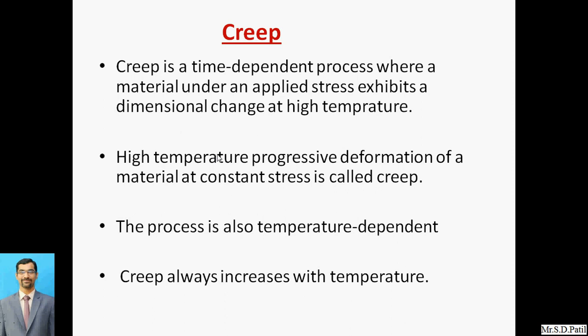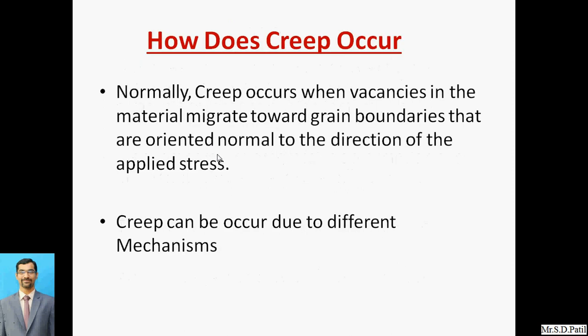In tensile stress, it is not dependent on the temperature. Creep is dependent on the temperature, that is the high temperature. So that particular deformation is carried out at a high temperature. So the process is also temperature dependent. Along with being time dependent, it is a temperature dependent process, which is not there in the tensile stress. So creep always increases with the temperature. This is very important.